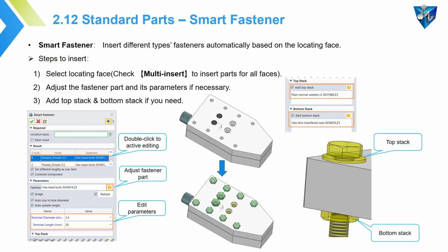Besides the common way, in fact, we have a smarter way to insert fasteners, which is using the smart fastener command. With it, we can insert the fasteners for different sizes holes intelligently. Okay, now let's move over to ZW3D to show you more details about this part.